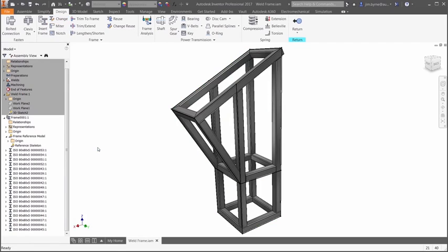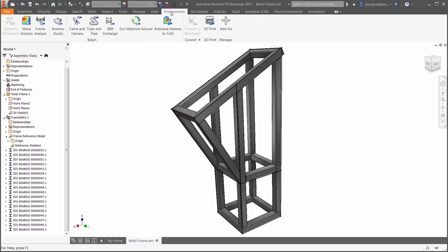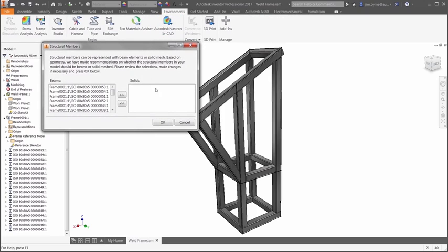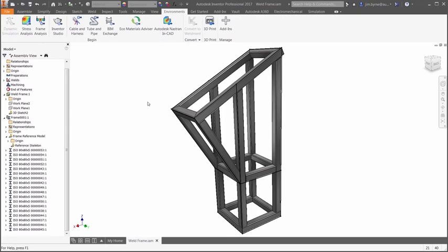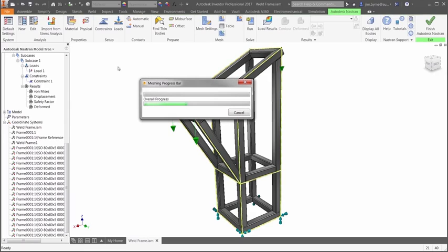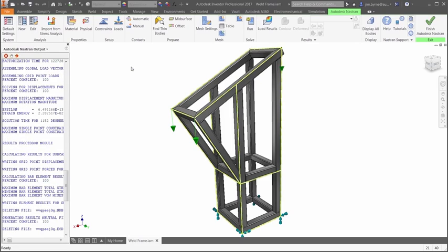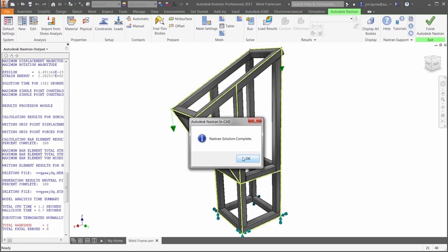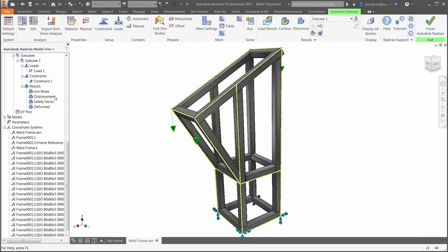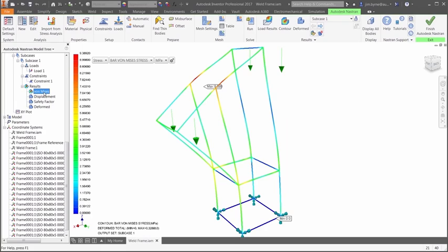The advantage here is everything we did in the analysis setup remains intact. After changing the size, the cross-sectional properties are automatically applied to the updated mesh. Simply rerun the analysis and determine whether your engineering requirements are satisfied. Beam elements are a great way to try several ideas in a short amount of time, as opposed to meshing the weld structure with solid elements which can take several minutes to solve.